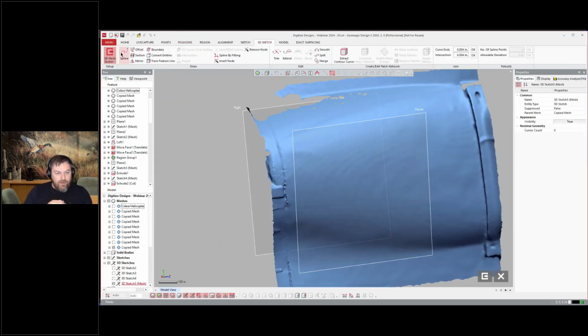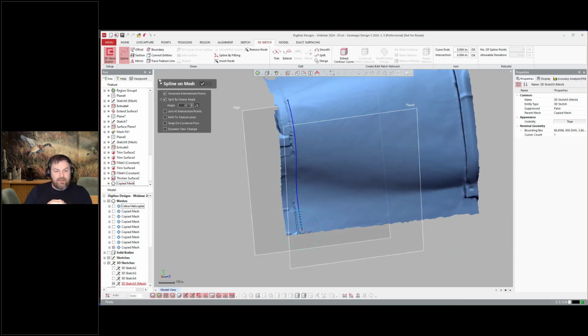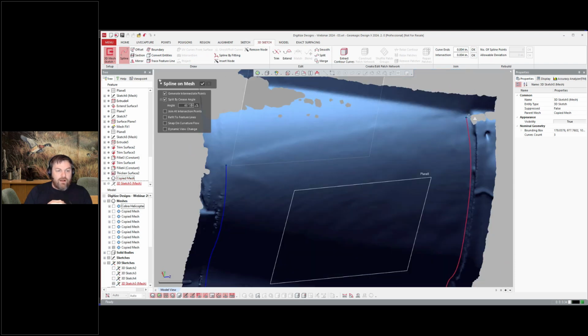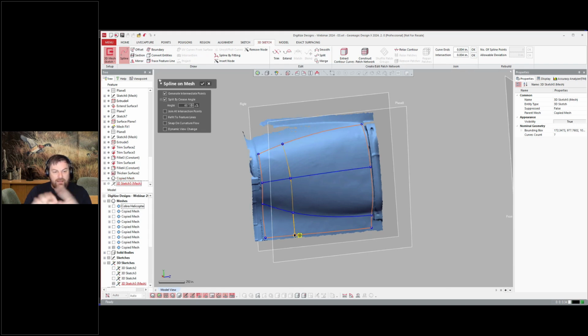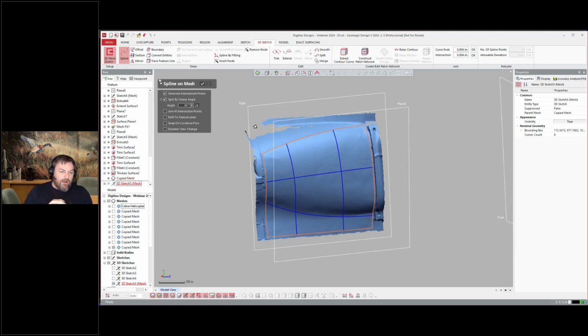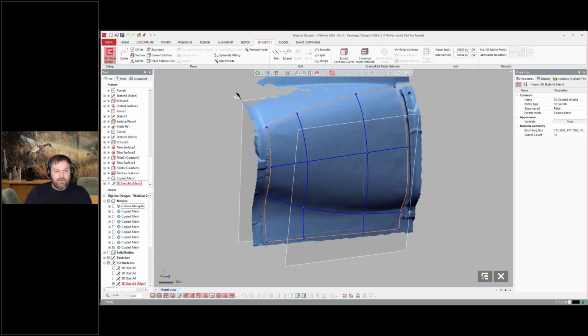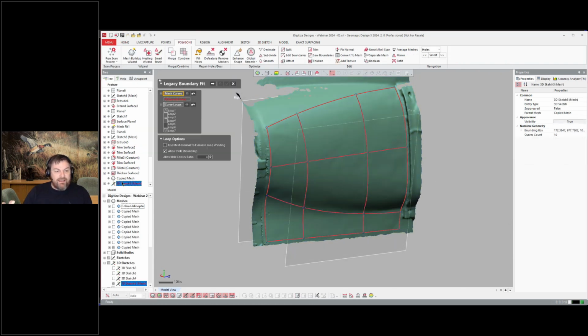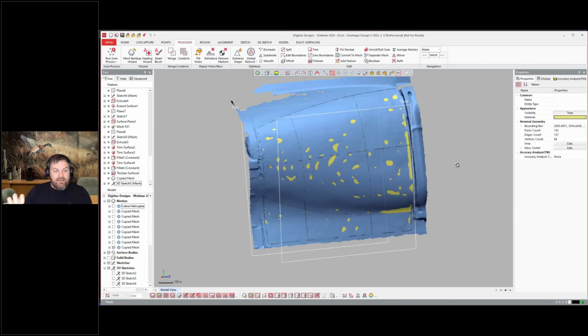So now, in this instance, I'm showing another piece of functionality that I really like to use a lot, and this is the boundary fit surfacing tool. You can just draw 3D curves anywhere on the shape. And these are along the lines of what the original designer might have done if he used CAD, or however they designed this originally, right? I can just draw out this curve network based on the curve components here, because that's another panel there. And I can say fit surfaces to these boundaries, yet the interior of those surfaces fits to the mesh. And you see it's editable.